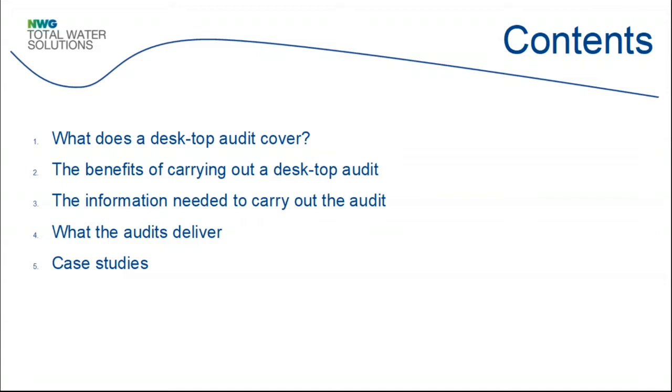I've mentioned trade effluent a couple of times. If you have a trade effluent agreement, a trade effluent consent, it's always really useful to see that and to see what sort of limits and levels are within that. So we don't need a lot to do this sort of first cut assessment, but a quick high-level evaluation of a small amount of the right data can really pinpoint potential savings and other opportunities. And it's very, very useful as a scoping study to make sure that you can focus your effort in the right places.